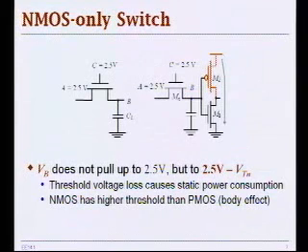Okay. Now, if it's not, then what happens if the transistor is not fully off? Then you have current passing through it. And what happens to that current? Is that actually useful current that you can use to charge a capacitor or something? Not really. Why? Because when you want that PMOS off, all the work is being done by the NMOS transistor, pulling stuff down. Okay.